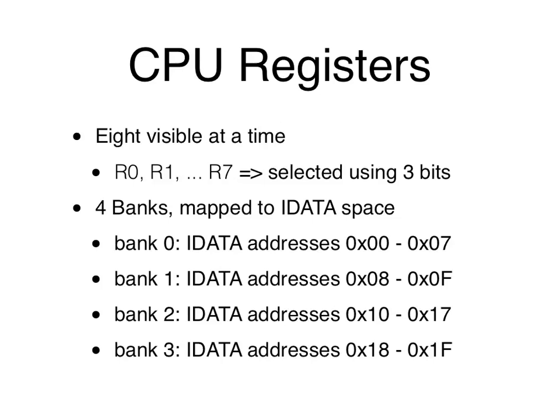And so it actually can encode instructions very tightly using just a few bits. Now, what 8051 does is you actually have up to 4 banks of registers. What does that mean? That means even though you refer to registers as R0 through R7, there's actually different sets of registers. You pick one set at a time, or one bank at a time.